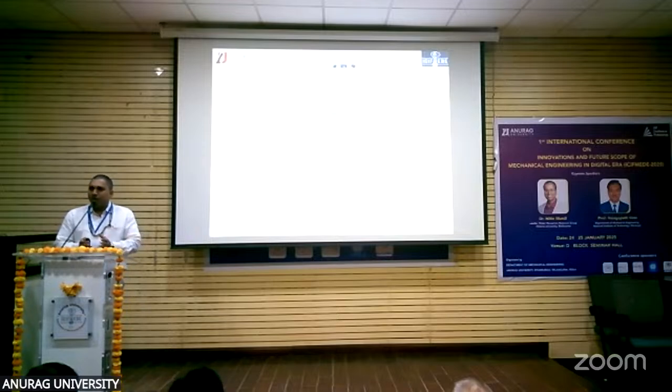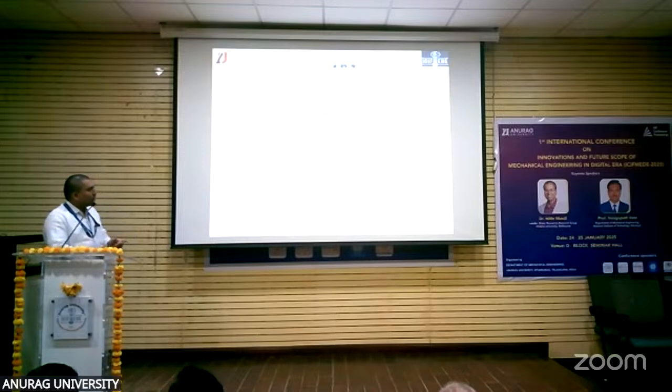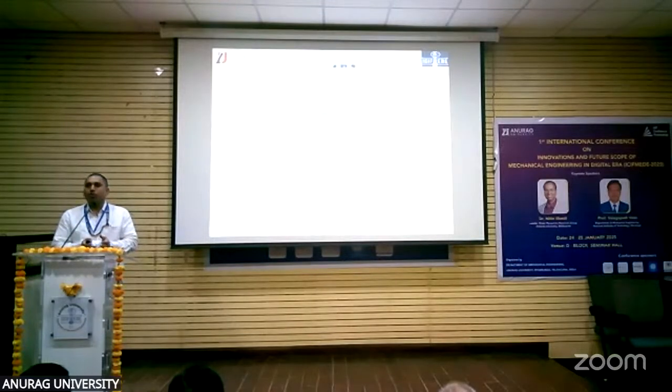When the humidity value increases in the atmosphere, that humidity reflects and refracts the sunlight. Based on that, the radiation falling on the solar panel will decrease. So finally, humidity reduces the solar panel performance. That is the main thing to be observed. And one more thing, ambient temperature: when the temperature increases in the surroundings, more radiation will be placed on the panel surface, so more heat will be absorbed. Finally, the power and efficiency of the panel will be increased.